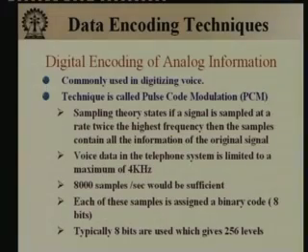Voice data in the telephone system is limited to a maximum of 4 kilohertz. Okay. This is a very good quality voice, so called toll quality voice, but this is not a high fidelity kind of sound. It is less than high fidelity, but very clear, for all practical purposes, for the telephone at least. If I limit the bandwidth to 4 kilohertz, we get some distortion, but nothing very noticeable. So, voice is still very clear.